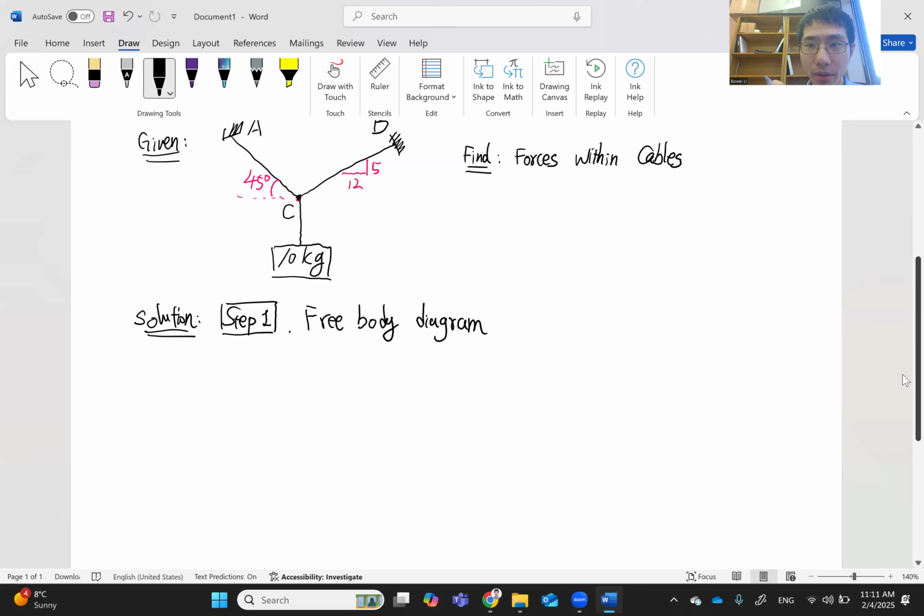A free body is where you cut out one piece of the system, a part, a particle, a point of the structure, and then you represent all the connections that used to exist at that point by forces. It might appear a little abstract, and we're going to look into that.